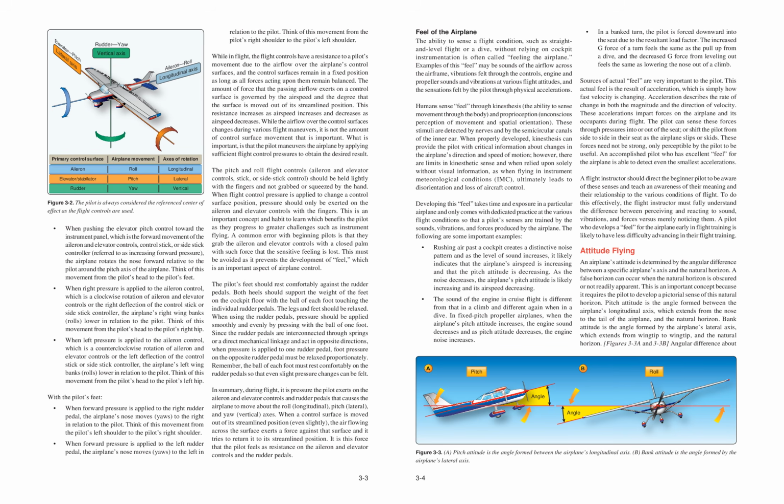3-3. Feel of the airplane. The ability to sense a flight condition, such as straight and level flight or a dive, without relying on cockpit instrumentation is often called feeling the airplane. Examples of this feel may be sounds of the airflow across the airframe, vibrations felt through the controls, engine and propeller sounds and vibrations at various flight attitudes, and the sensations felt by the pilot through physical accelerations.